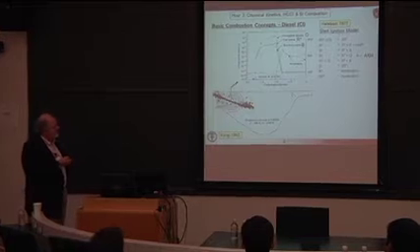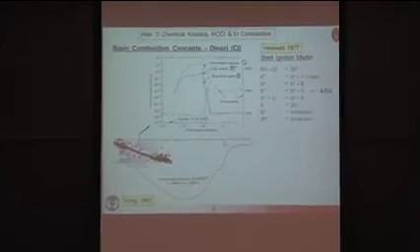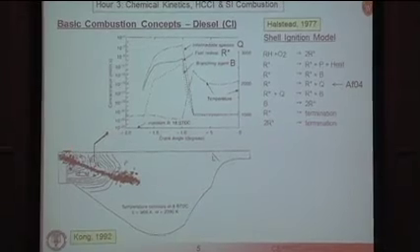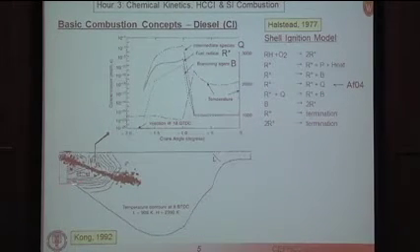So for diesels, we have this situation. We inject the fuel into the combustion chamber. I'm showing you just one spray plume here. At a certain moment, we get ignition. Here's the injection crank angle, in this case 18 degrees before top dead center, which is over there. And it just sits and cooks for a while. During that cooking process, we create radical species, intermediate quasi-steady species or stable species, and eventually at a certain point it all goes off and we get a big increase in temperature. That corresponds to the ignition.